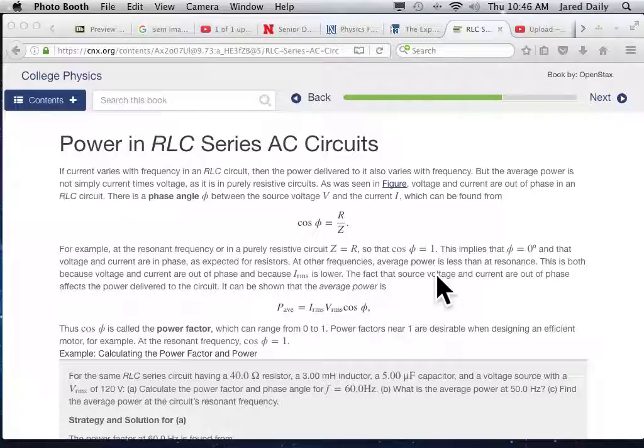the right frequency. If it's the right frequency, you'll get a big current coming through and you'll be able to hear the voice of the person you're talking to. If it's not the resonant frequency, you will not get a big current, and you will not hear the voice of the person. So phone calls that are not the right frequency, you won't hear. Phone calls that are the right frequency, you will hear. And you can adjust that frequency by adjusting the inductor or capacitor, or both.